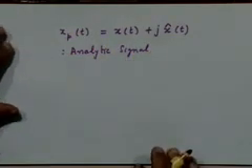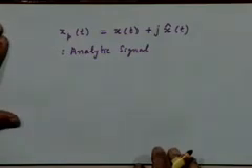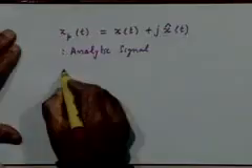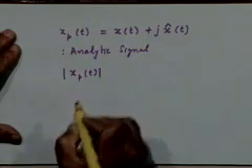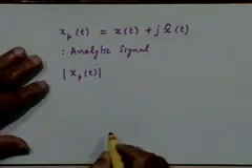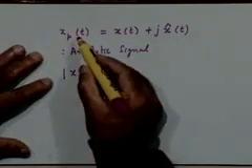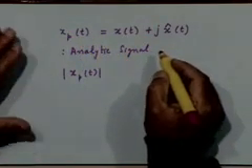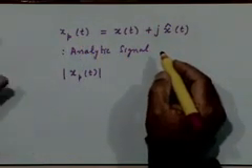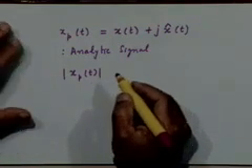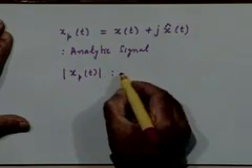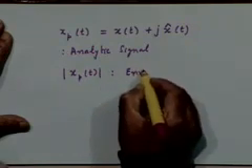One of the motivations that I gave you for defining the signal, and we have to appreciate that a little more as we go along, is that x sub p of t is also called the pre-envelope of the signal x of t, and the magnitude of x sub p of t, the modulus of x sub p of t, would be the envelope of x of t.